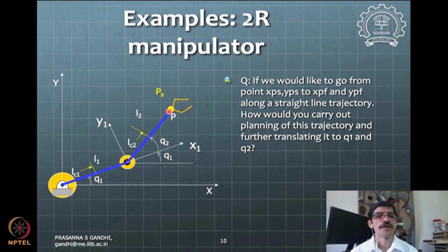Okay, and I'm given that while on the trajectory I can be off the trajectory by some delta amount. Okay, so that is what is given as a user specification, which needs to get translated into sensor specification eventually. Okay, so I want to go along this trajectory, and I cannot be off the trajectory by more than plus minus delta amount, and then how do I go about getting the sensor and actuator specifications.